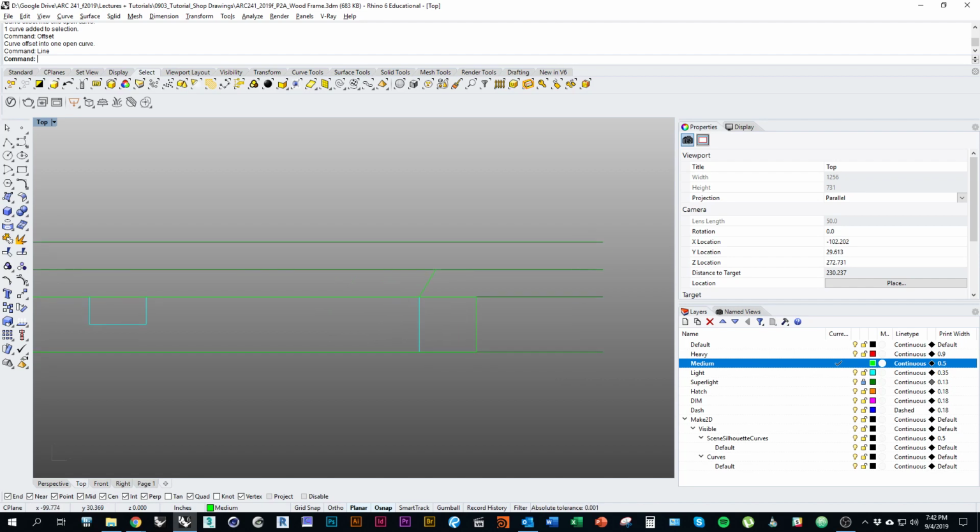Now, technically we're not actually drawing this thing in the right dimension for an oblique, what we're doing here is drawing this at 5/8 because that's the depth of the joint. So even though we're representing it at an angle, when we go to dimension that, it'll be clear that that's the correct dimension for that part.